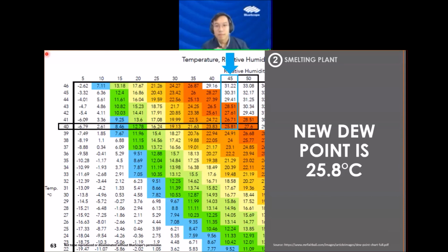Okay, next question: can you provide some examples of vapor barrier that are available or currently in use in the market? If we are talking about vapor barrier, just now I mentioned the characteristic of a vapor barrier is that it needs to shield the vapor, also called steam or water moisture, from going through the membrane from the barrier towards the roof. So you can have some kind of polymer membrane, right? That is closed cell and doesn't transmit water through the membrane.